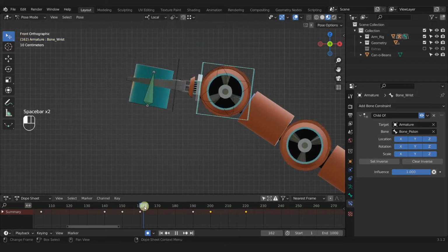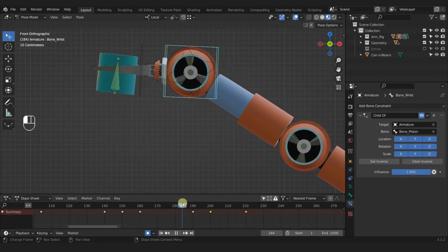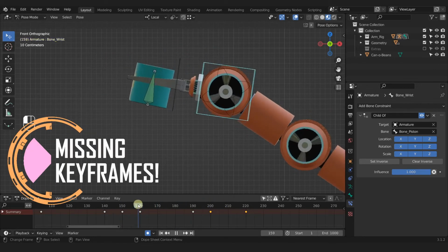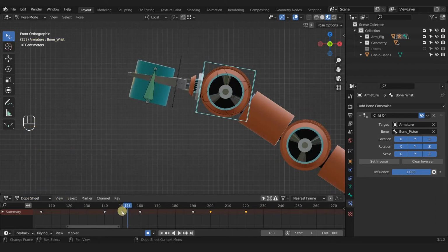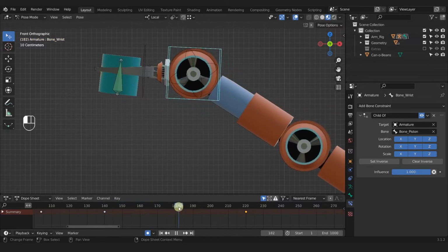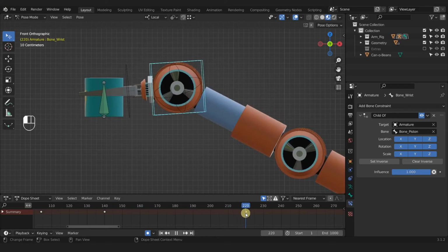Okay, so this is starting to rotate because I didn't add my rotation keyframe. So I don't want this to start rotating right here. And if I'm going to guess, the last keyframe where this is set before the last one is going to be 150. So let's just select this one and go to selected only. Oh, it's actually 140. So it's actually calculating from here to here. So it's going to start that rotation right here, and it's going to start slowly rotating all the way until it comes to here. And I don't want that.